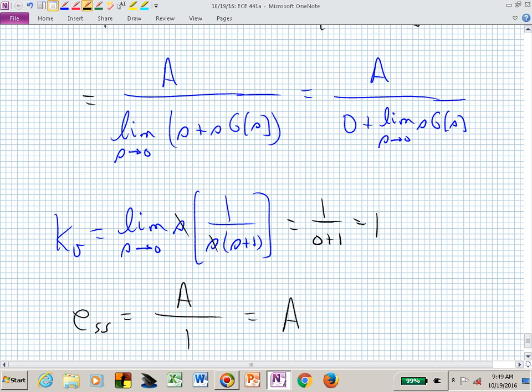Now our system can keep up. We have a bounded error, but we're tracking our reference input. If we wanted to do better, we would throw another pole at the origin, and then we would have 0 error to that ramp. But now we would have two poles at the origin, and our system is much more difficult to stabilize. But these poles at the origin give us a good thing for steady state accuracy. They make it more difficult to worry about the transient or the stability of the system. But I hope that that's now been brought home from today's class.